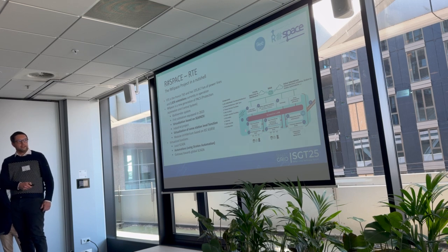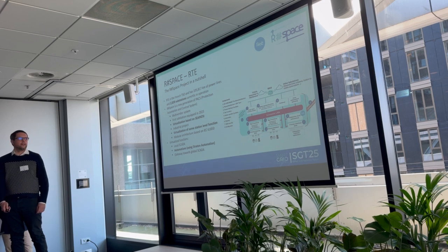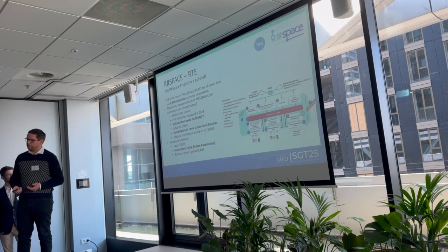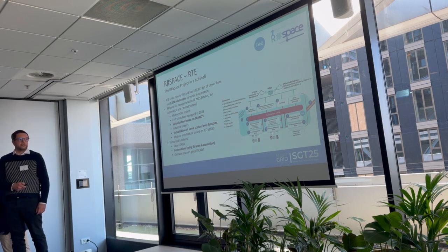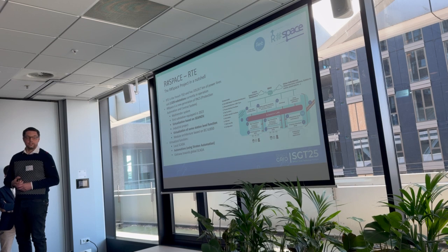So you have here an example of a station. We still have physical devices for the bay functions, for instance. So we are still using vendors providing physical devices, physical IEDs, but for our station level functions, we are virtualizing it. For instance, the local SCADA, we have it there. So station operator functions. The gateway also is virtualized, so it's a gateway to send the information toward the global SCADA for dispatchers. And finally, I will focus today on the substation level automations, for which we are using Straton automation.